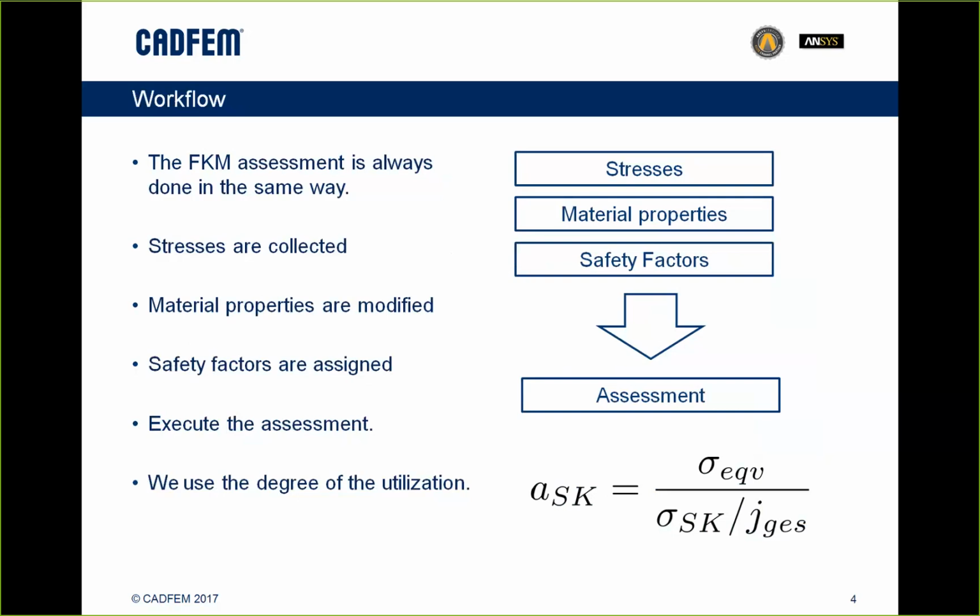So what we have is some material factors we calculate in to compare the sample we have to the real part we have. So my material properties will suffer a bit, but will then be closer to reality. And because we are closer to reality, we need some safety factors.